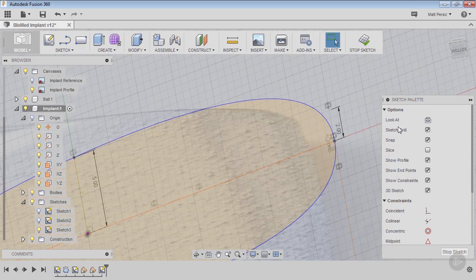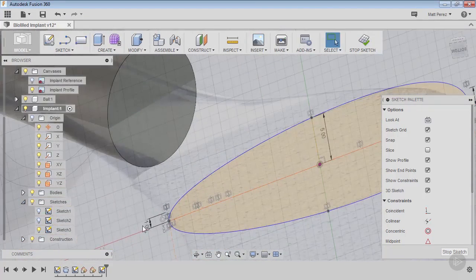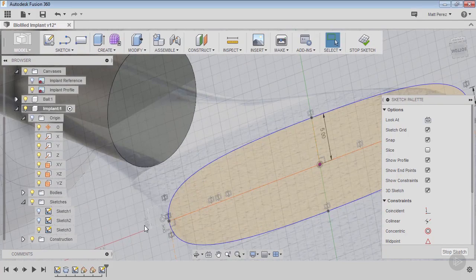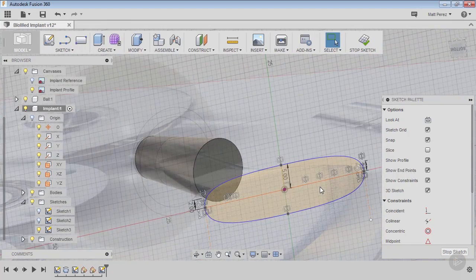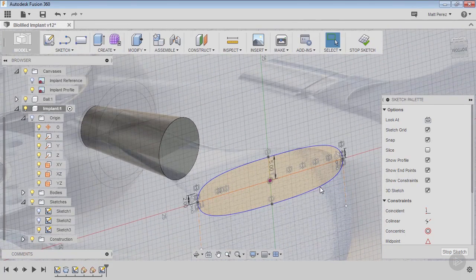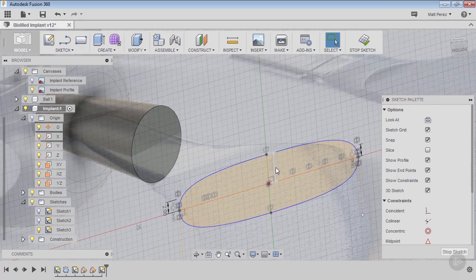We can say that we actually want this to be 2 millimeters on this side and 2 millimeters on this side, and you can see the change that it has in the profile. So depending on the design, depending on the intent, what we might want to change later on, we can control those things. And notice that now that the mirror is in there, it does have a mirror relation, and it's able to modify those as well on the bottom and the top.